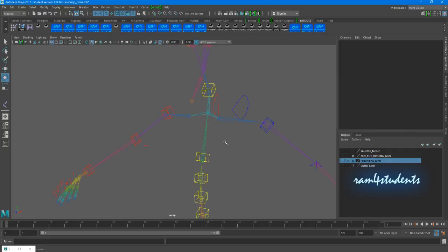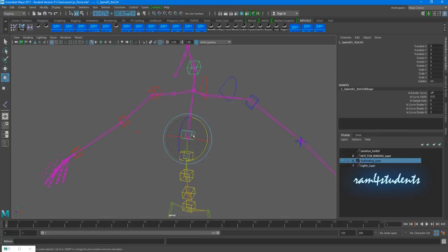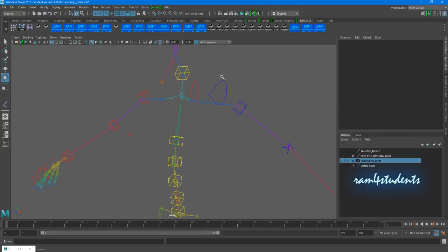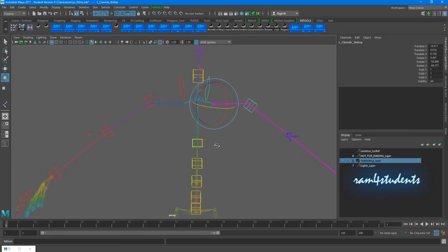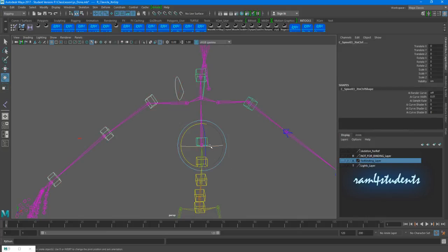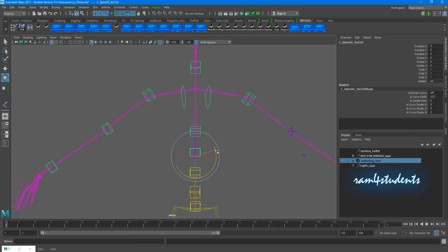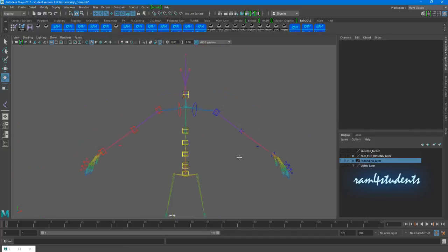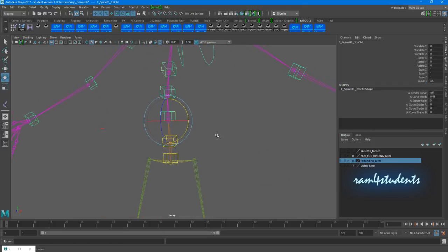So right now I need to parent the clavicle groups also to this spine 3 joint controller. So select the clavicle curve, up arrow so that you will select group node and shift select the curve, parent it. You can do the same stuff, select the clavicle, up arrow, then shift click and select the spine controller curve. Now, okay, it's working now, but there are still more controllers you need to do. So if you check here, it's working now.